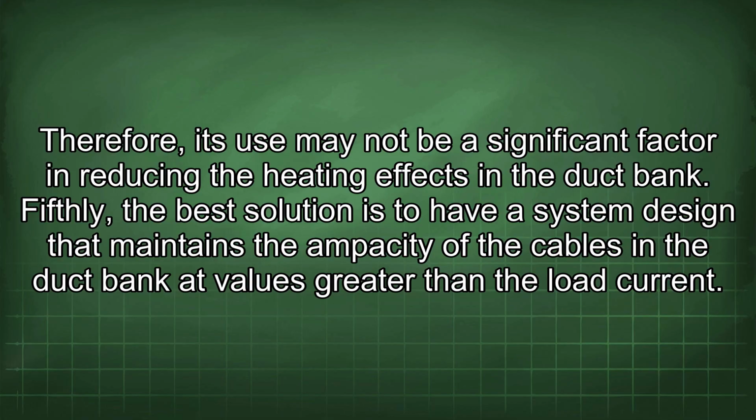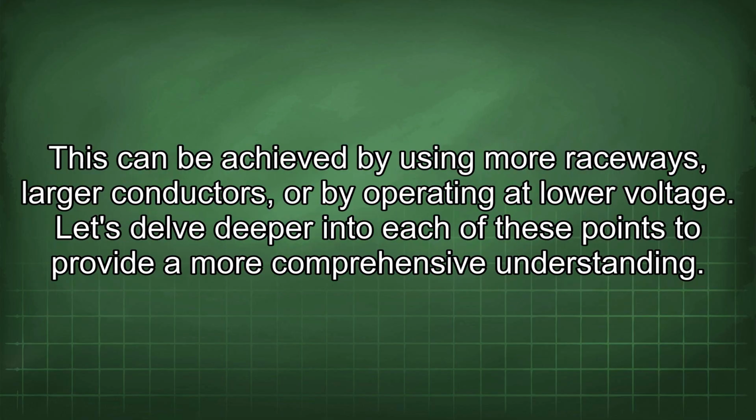Fifthly, the best solution is to have a system design that maintains the ampacity of the cables in the duct bank at values greater than the load current. This can be achieved by using more raceways, larger conductors, or by operating at lower voltage. Let's delve deeper into each of these points to provide a more comprehensive understanding.